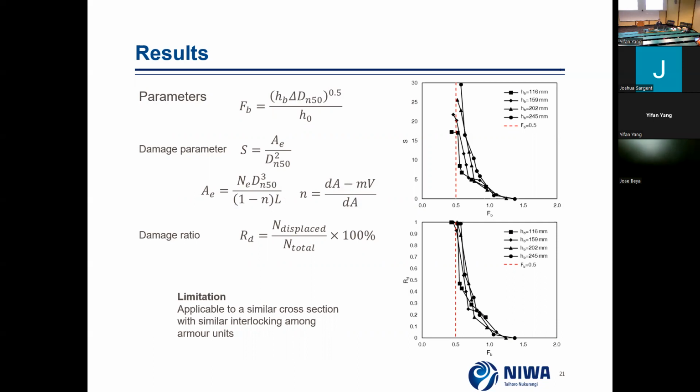The stabilizing strengths include the effect of breakwater height, HB, the relative density of the units, delta, and the size of the unit, dn50. And the destabilizing strength is H0, which is the maximum depth of the tsunami bore.